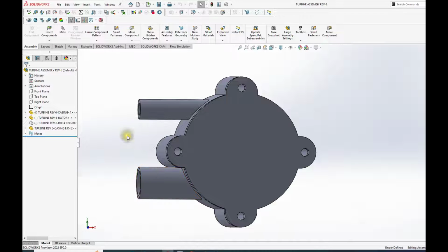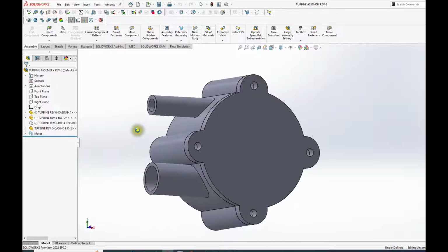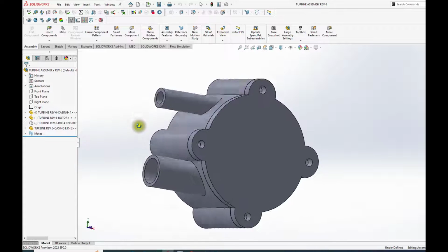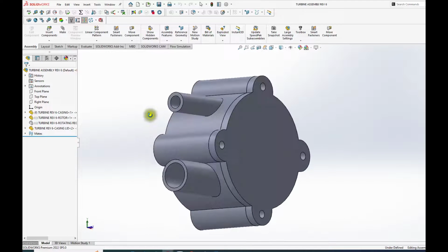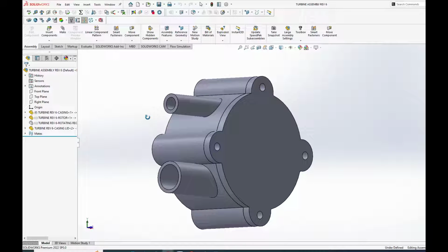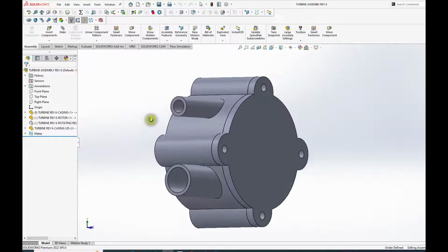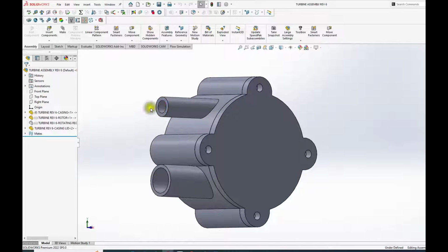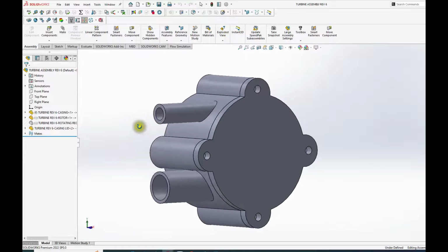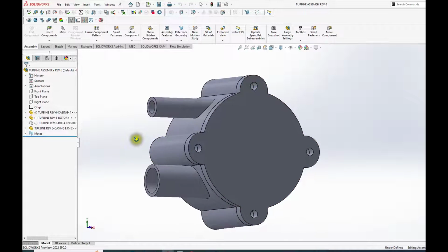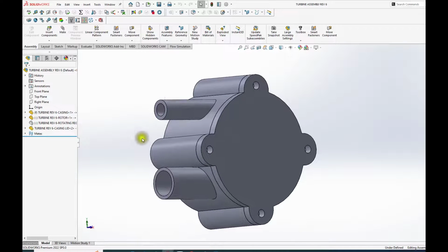and we're done. Now, what is missing here is where we want to go from here. Well, basically just do flow simulation to see how much energy, or in this case power, can be extracted from this tiny turbine under some flow condition that we're going to be specifying. Like for example, the pressure here is water is coming from your aqueduct system, so that probably will be about 40 psi in, and a flow rate between around, I don't know, between 1 to 5 GPM getting in and out. So under those conditions, then you're going to see how much energy can you extract from this turbine. So let's go flow simulation.